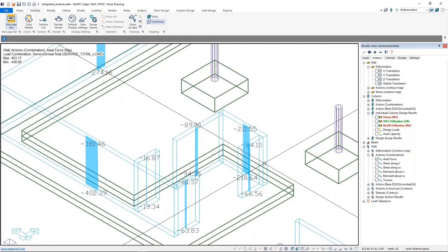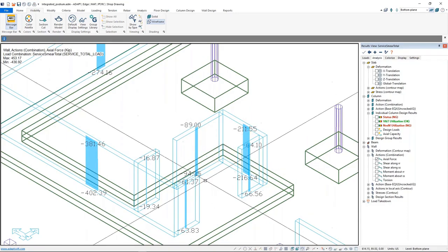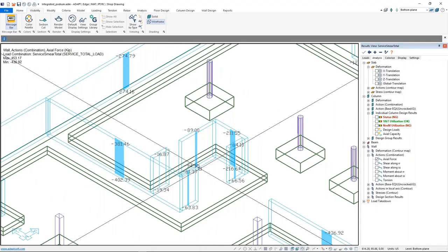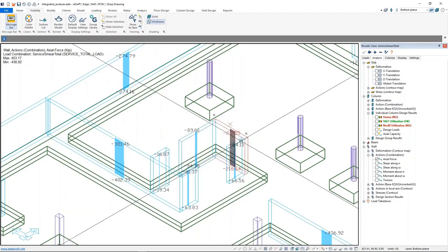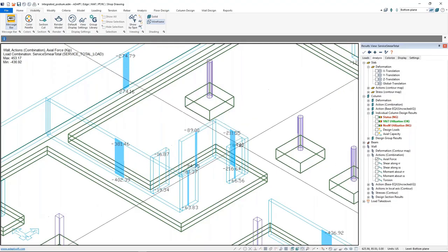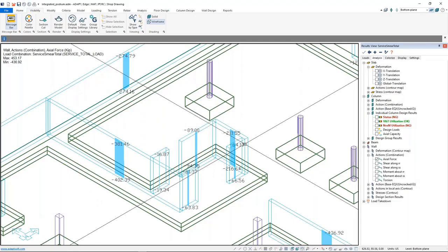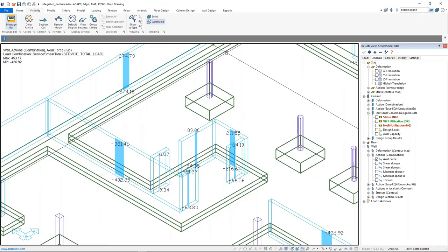Or let me step back. The analysis works on the composite C or L or any shape. As you might know, ADAPT doesn't restrict how you model your shear walls. However, to give you a specific answer for your wall design question, each wall is designed as its own individual panel. However, we do provide a combination diagram that shows all of the end zone reinforcement to help with the final detailing. But the design is based on each individual panel. So that was one of the questions.